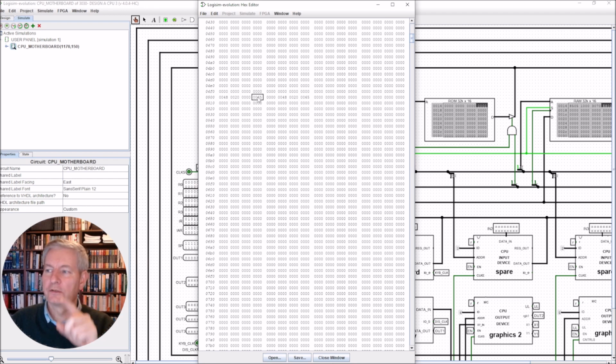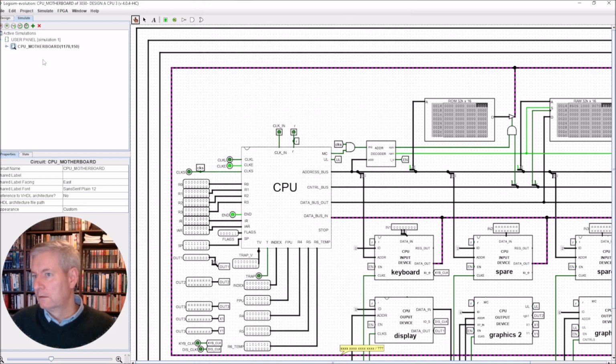So it becomes H space E. H is 48, the space is 20, E is 65. And the next one here, 0000, is the string delimiter. So that's it worked, and that's how we generate our ASCII and how we place our ASCII within our memory location. So that's it for the string values.